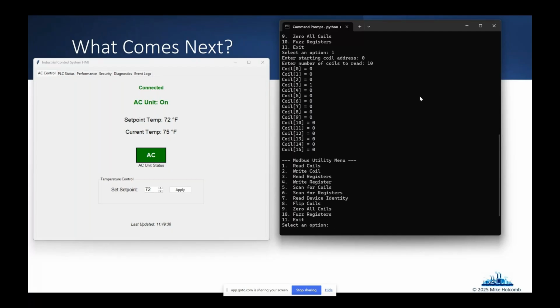Here I see a bunch of zeros, and then I see, ooh, the fourth coil, number 3. It's zero-based numbering, which I hate, but it is what it is. So the fourth coil, that's a 1. I might think, and this works in some control systems, does that 1 indicate whether the air conditioner is on or not? In this case, we'll just cut to the chase. It does.